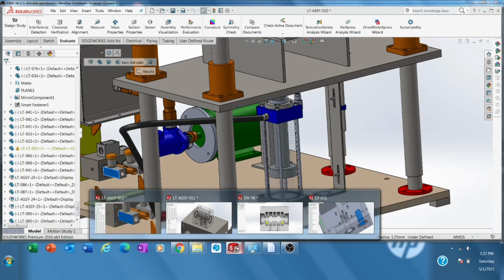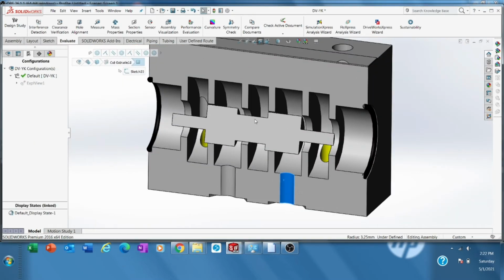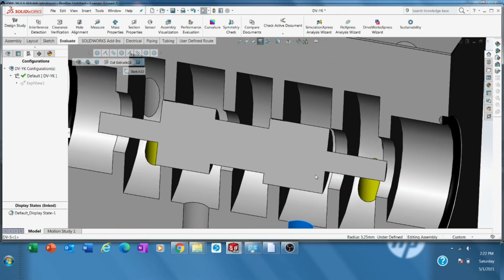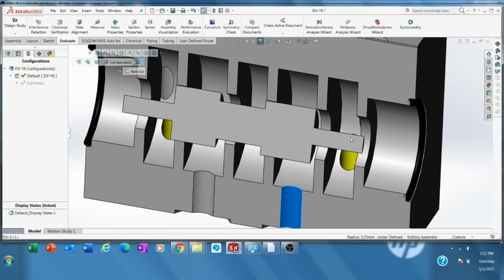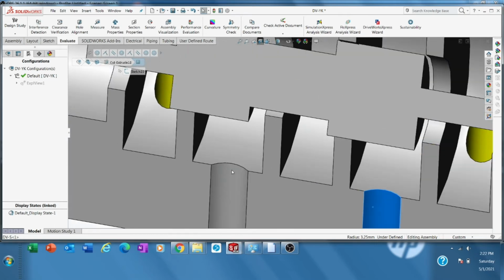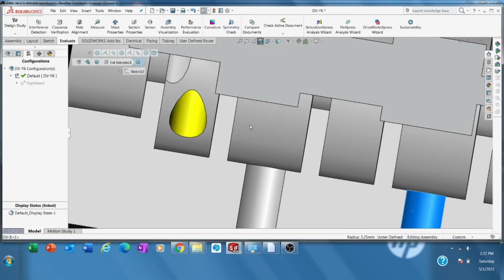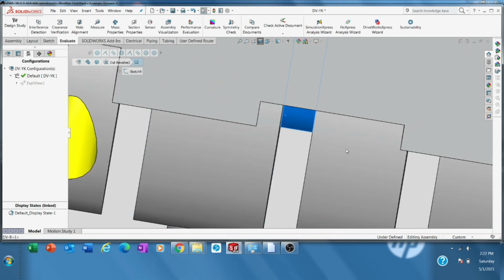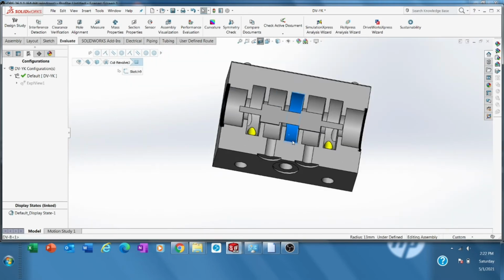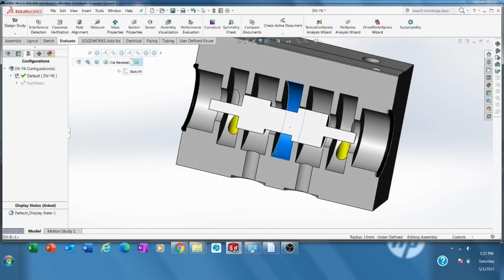So it's very easy now because we already explained that. So this pressurized oil moves to here, the oil goes to the A port, and oil from the B port returns to here. Okay, returns to here, and then goes to the next chamber, and the next chamber, as you know, is the tank.